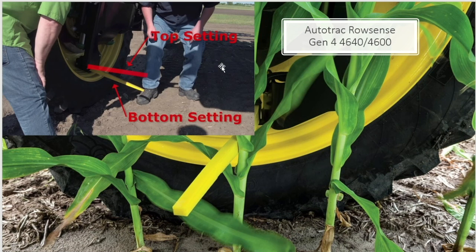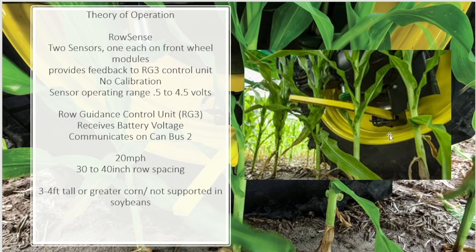Down here at the bottom, there are 2 positions to the RowSense one. There's a bottom for early season corn, and there's a top setting for your larger corn. And in between this paddle, if you're experiencing some issues with the system, it doesn't seem like it's working correctly, we need to make sure that there's no debris or mud in between this paddle.